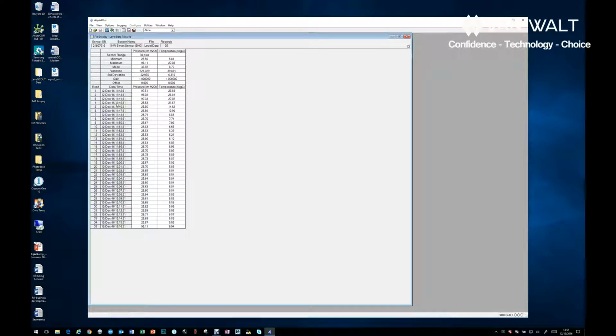You can see 11:45 is when we actually have water data. Our manual dip's been applied to all the readings, and because it's not moving, it's about 25.5 centimeters, give or take a small amount, for the rest of our data set. Apart from at the very bottom here, you can see we've taken the sensor out of the water and it's reporting a cable length again.